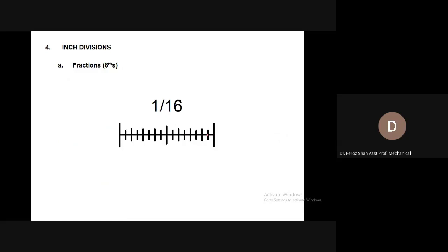You can go beyond this as well. Divide again this line segment from here to here into two equal parts and go on and on dividing all the other line segments. You will finish with 1 by 32. You can go beyond this, 1 by 64 and so on. So you can see that you can go up to any fraction through your own cardboard scale or a scale drawn on a harder sheet, in this case, a cardboard.